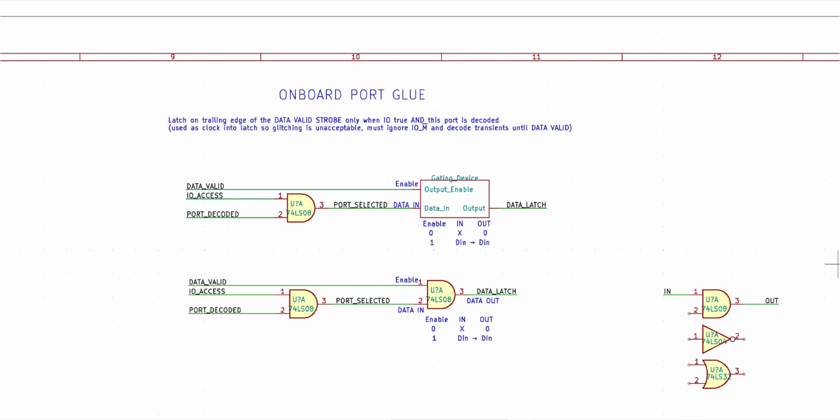Again, these are still just functional signals. They're not connected to actual board signals. So that's our next step. As I mentioned, one advantage of using functional signals is that this circuit is still processor independent, and it's not tied to any specific logic levels or timing or actual signal names. But it's time to assign actual signals, and let's look at the data valid strobe first